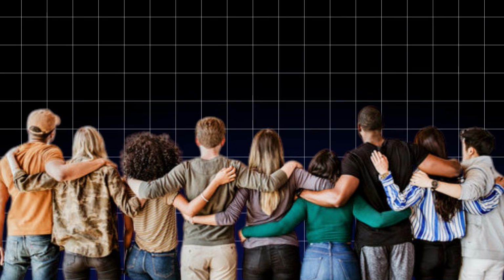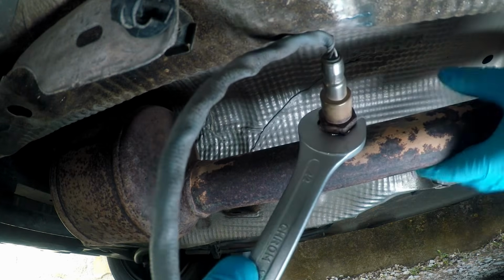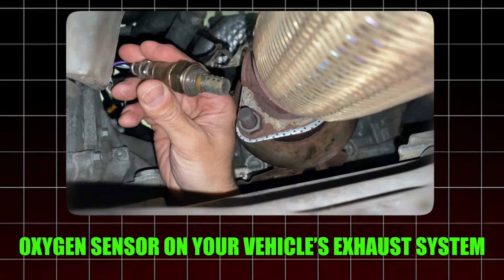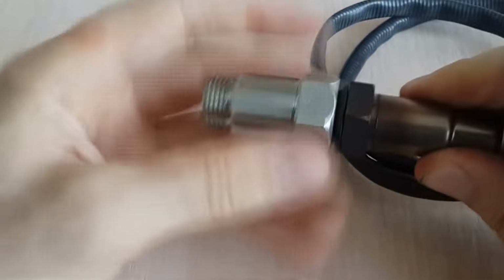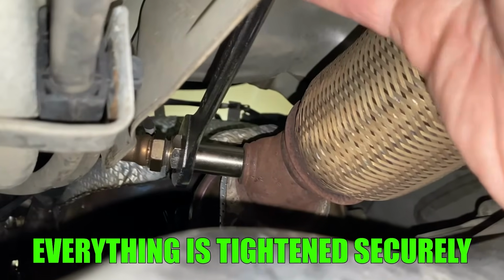For those who still choose to use O2 spacers, it's crucial to weigh the risks carefully. If you proceed, the installation process is relatively straightforward. First, locate the oxygen sensor on your vehicle's exhaust system. Then, carefully unscrew the sensor using a wrench. Install the O2 spacer onto the sensor, reattach the sensor to the exhaust pipe, and ensure everything is tightened securely